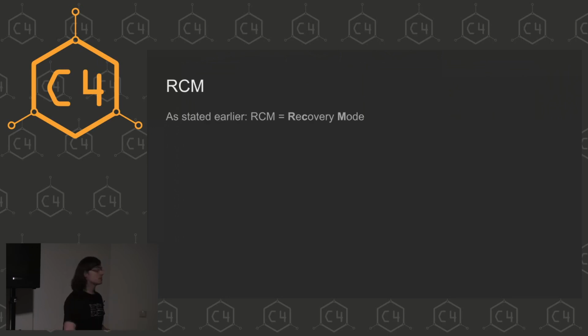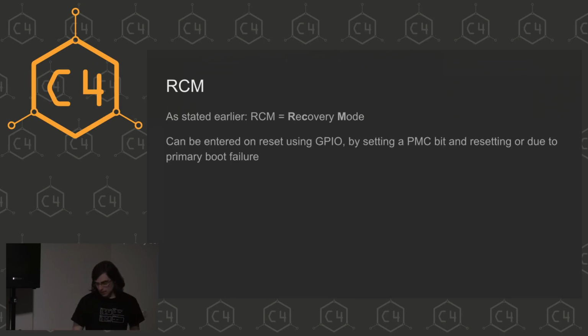RCM, as stated earlier, is the other path that you saw earlier when you press a magic button combination or the thing cannot boot. It stands for recovery mode. This mode can be entered on reset using some GPIOs if you press a magic button combination, or if you set a magic bit somewhere. You can trigger this by software by setting a bit in some register and then resetting the board.